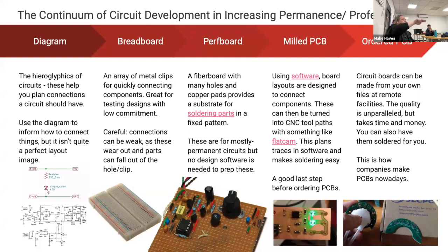And they are connected in rows across the breadboard. So you can stick the connections in, make temporary connections, and then add additional connections in between rows using wires. But the parts can fall out, the springs get worn out, and your graduate TA can come through and just pull all your wires out when you're trying to debug your circuit, because usually the problems are in the wires. So my graduate TA would come and just pull all the wires and make you do them again.